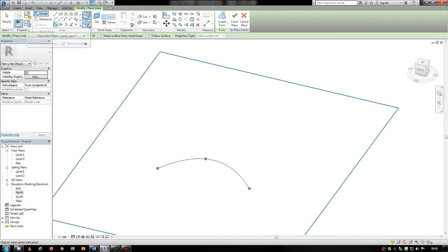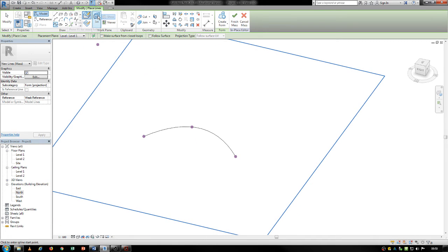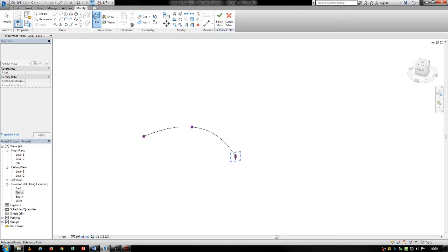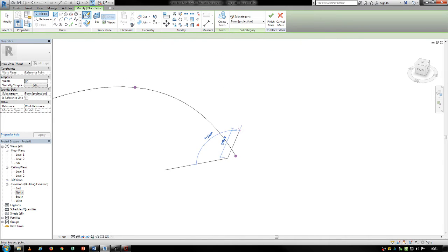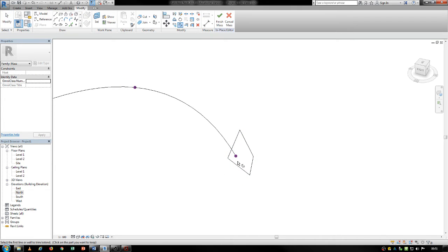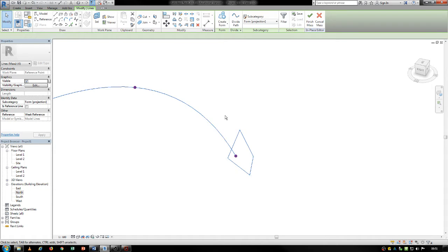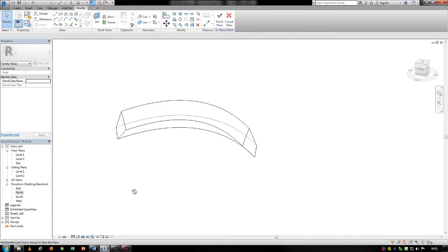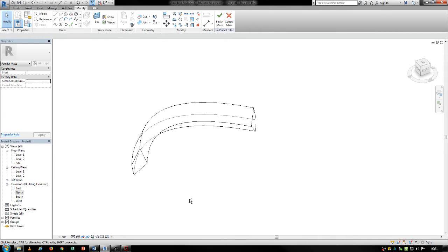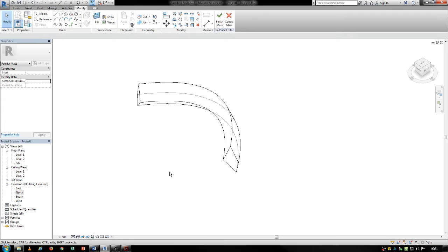It's very important to define the right plane that you draw on in massing in Revit. So I would set my work plane, and then I would go on one of these points to define a new work plane, for example on this one, and then I would draw something else, let's say that geometry, make sure it's closed, and then when I select this and that, and say create solid form, it will make that loft form for me, or the sweep form for me in Revit.